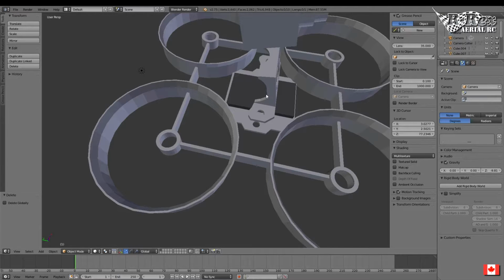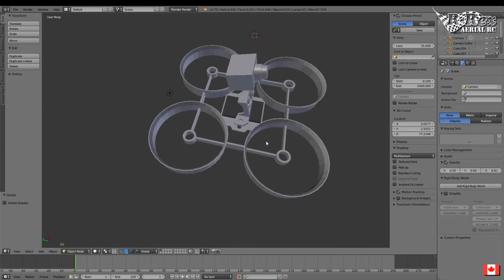It'll stick it together, but if you really need to pull the motor out, you can work the motor out. The silicone will let go as you're pulling the motor out. So you can glue your motors into your positions and hold them down. The last step, though, is because we are landing on the feet of our motors, that's going to cause some harm to the wires. So let's make some quick little wire savers.